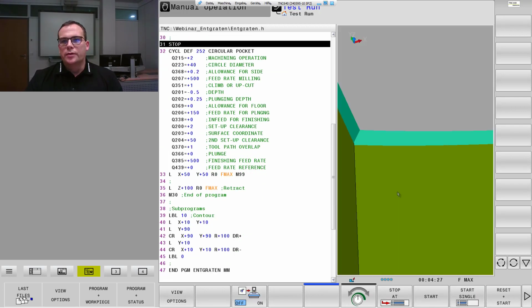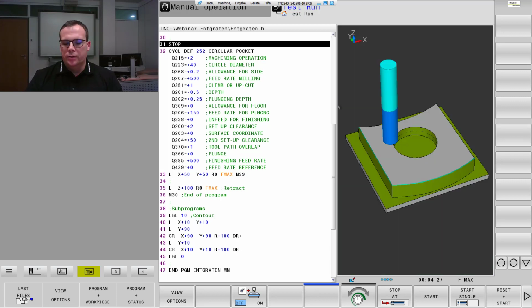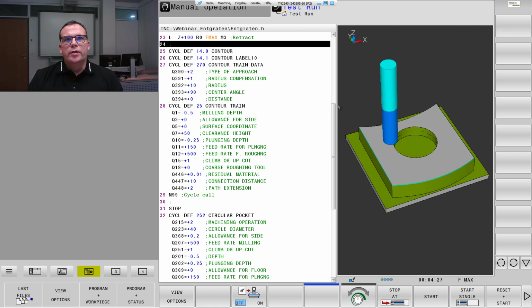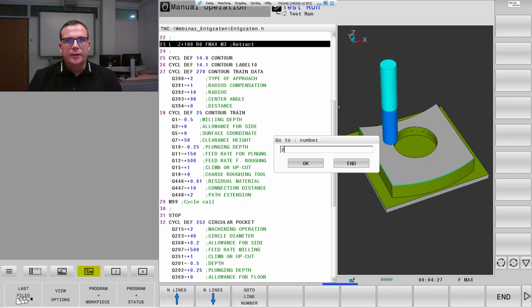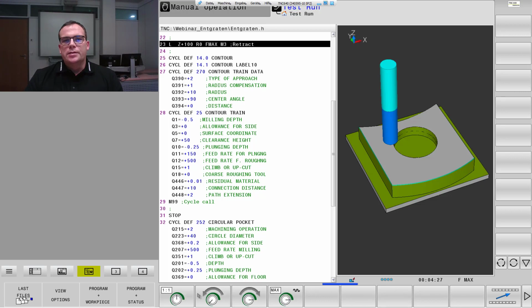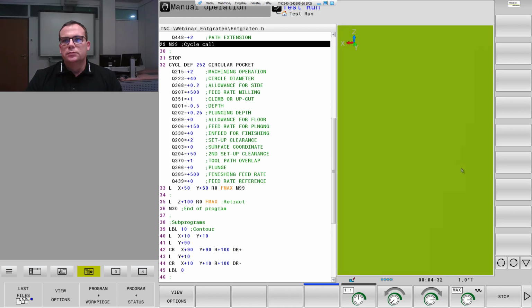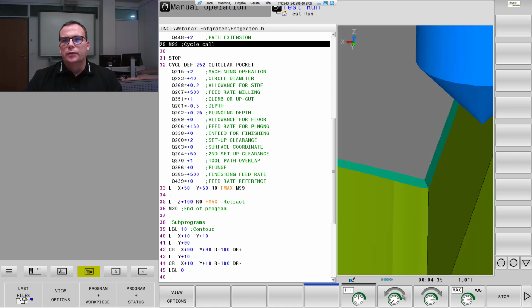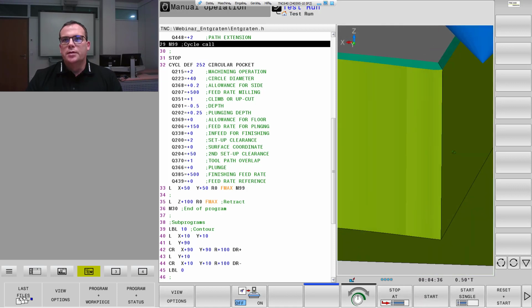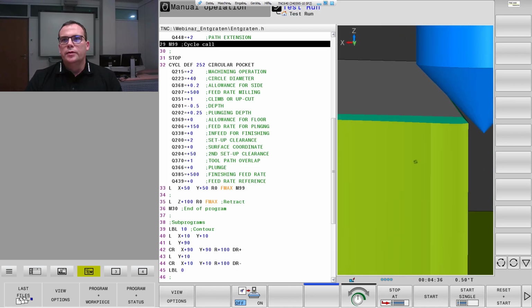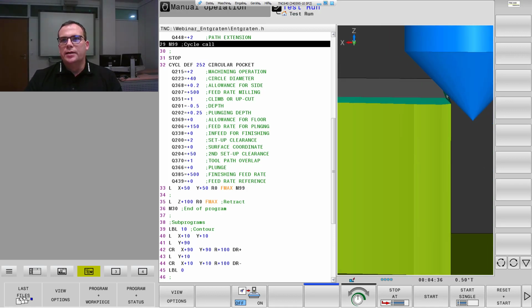And now we saw that the chamfer is already on the contour here. So let's make it a little bit slower. Yeah, and here we see that the tool is guided exactly here on the cutting side on the 45 degrees. That's because of our delta length and delta radius.